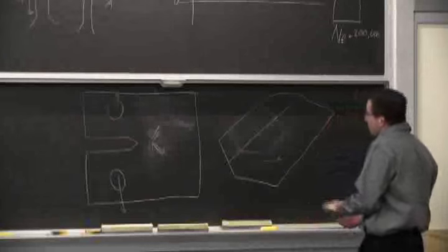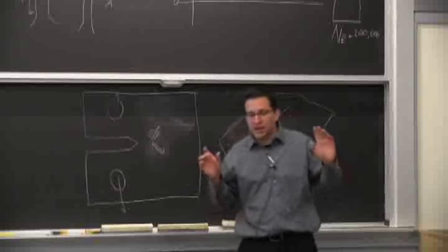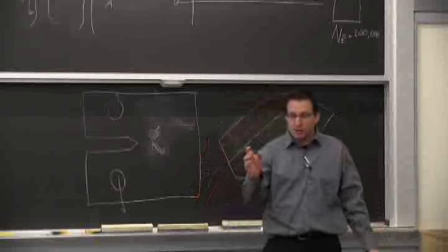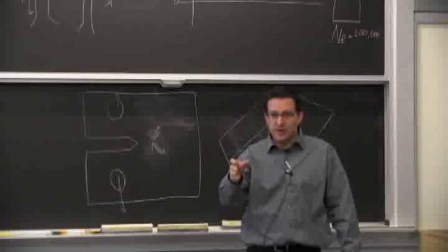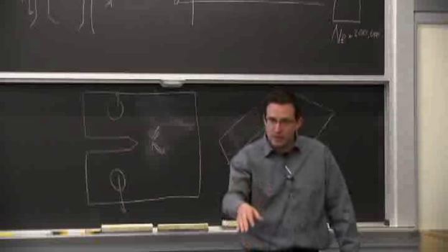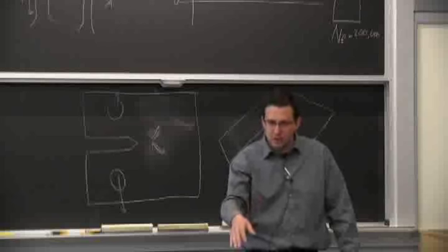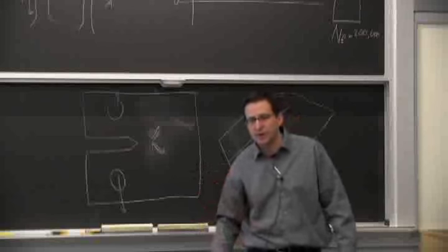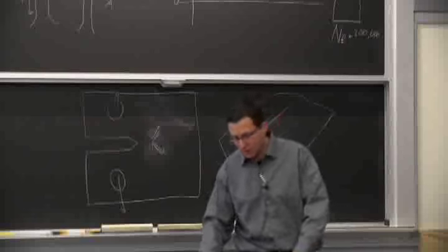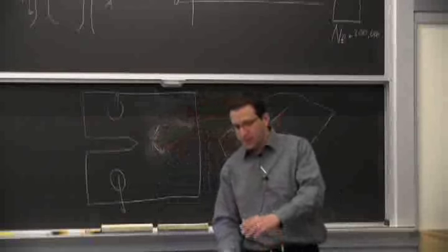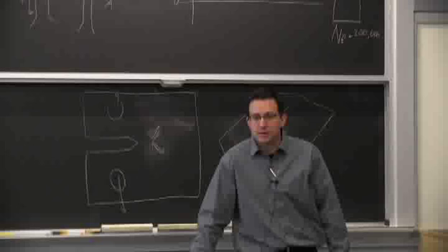Well, okay, so what we talked about is mostly unidimensional. And if you go to FEA, yeah, you'll look for max principal, because it makes sense for that max principal to be a location of initiation. So you have to identify your location of initiation and look for the maximum tension there. And if you have combined loading, you have to include other factors. Right now, we've been concerned with a crack this way, and we're trying to open it up this way, but we'll definitely talk about how sometimes you can have multiple loading conditions applied.